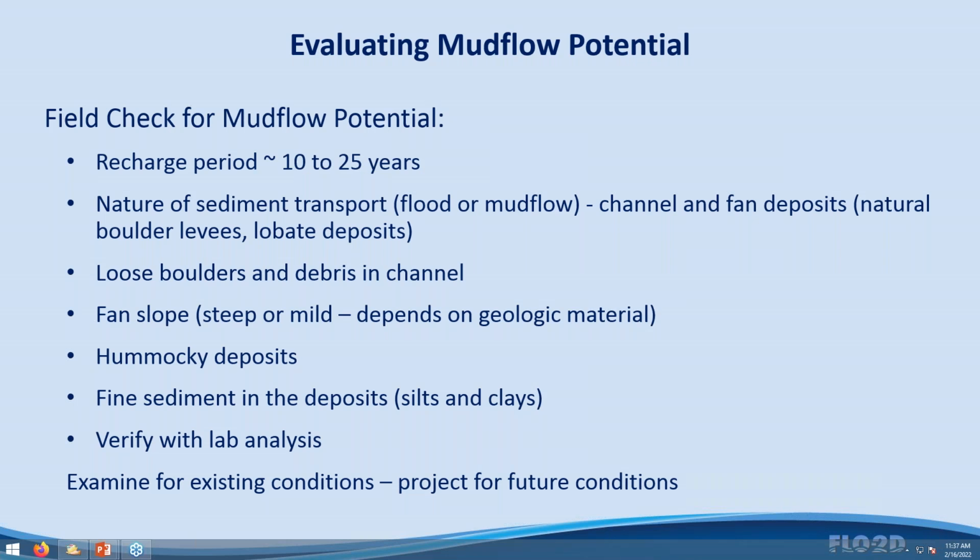Some watersheds, and it depends on the geology, of course, may only require a 10-year period in a more wet environment in order to significantly store and recharge the lower part of the basin, mostly the channel, with sediment. And this may involve 2 or 3 smaller events, on the order of the 2-year event, or maybe a 5-year event, where the frontal wave brings some material down, maybe past the fan apex, past the mouth of the canyon, but yet leaves a lot of material up in the channel.